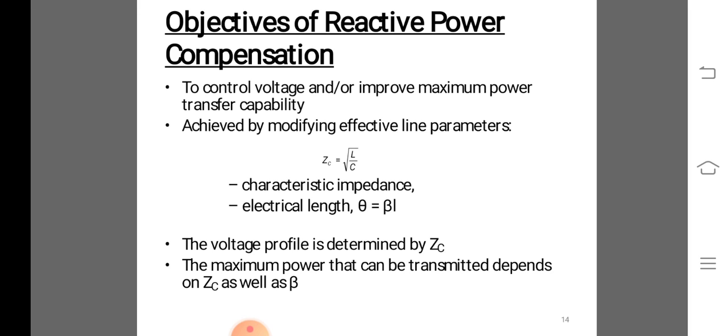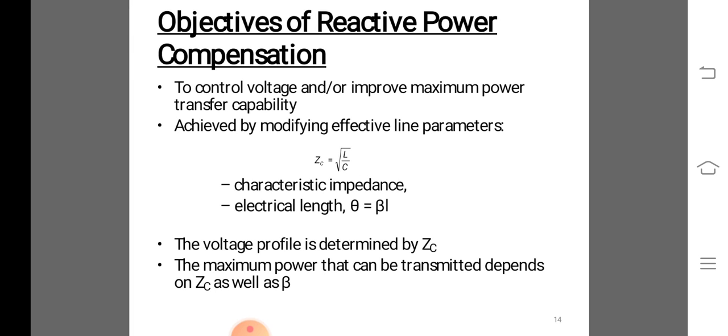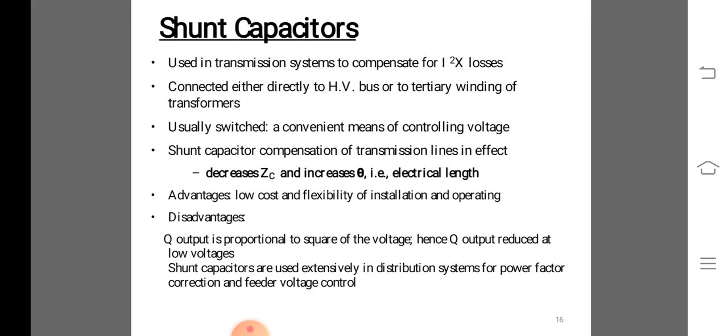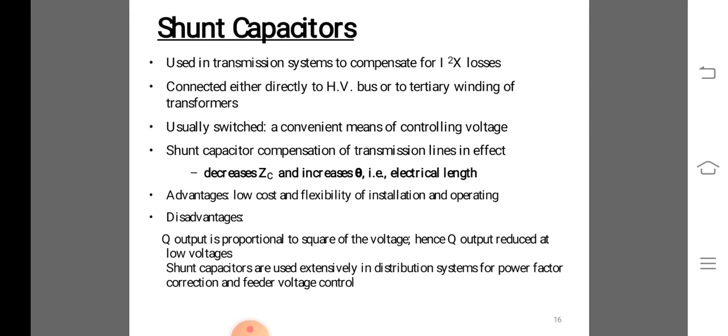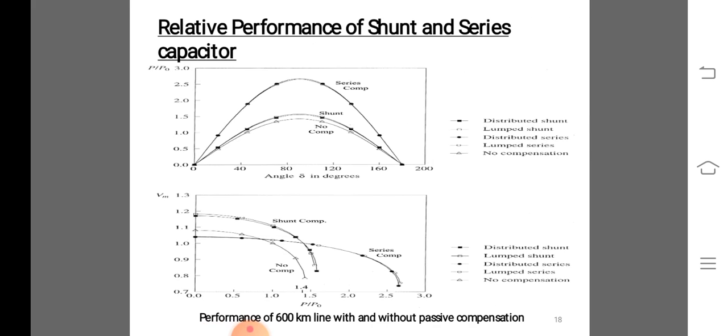The transformer core has a non-ferromagnetic gap to provide the required linearity. Some of the following objectives are maintained in the compensator. The compensator's reaction should be possible, fast or slow, whenever demanded. No switching of capacitor should take place at that time, to avoid additional transients in the system.